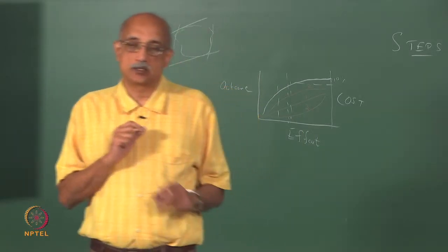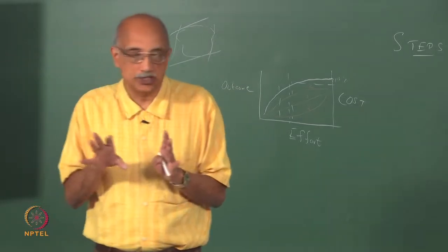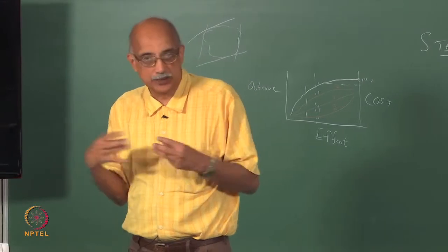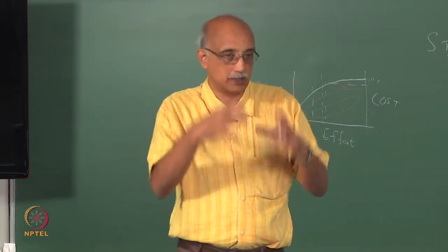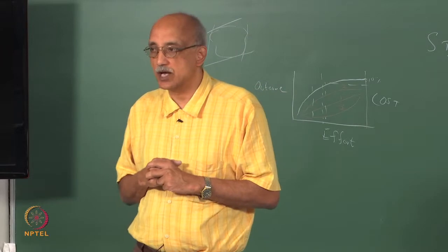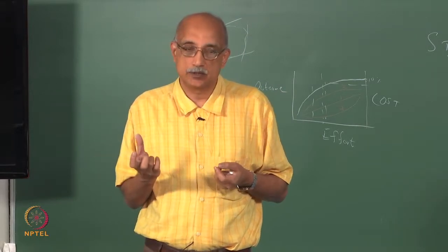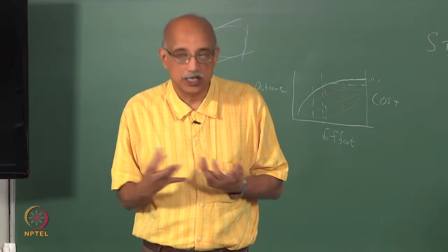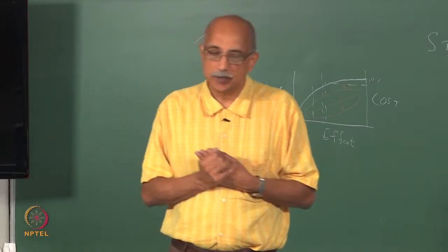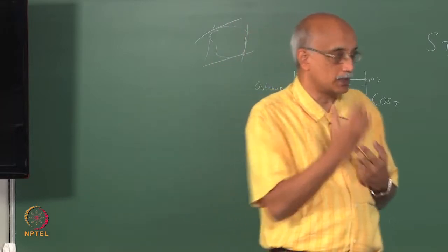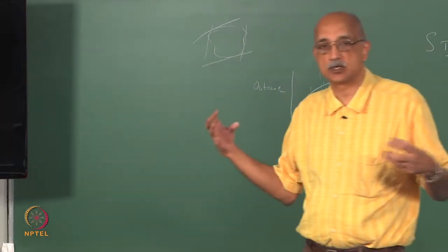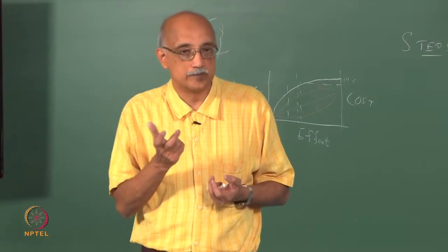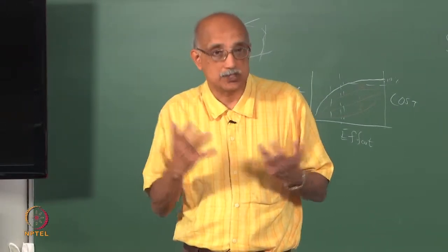You can imagine that if you have an assembly of particles that are all uniformly shaped, let us say they are all spherical, the way they would compress, or the porosity that this population of particles would have, would be very different than if you had a set of highly irregularly shaped particles. So, simply by looking at how the porosity of the sample changes based on a compressive force, you can assess how non-spherical the particles are on average.